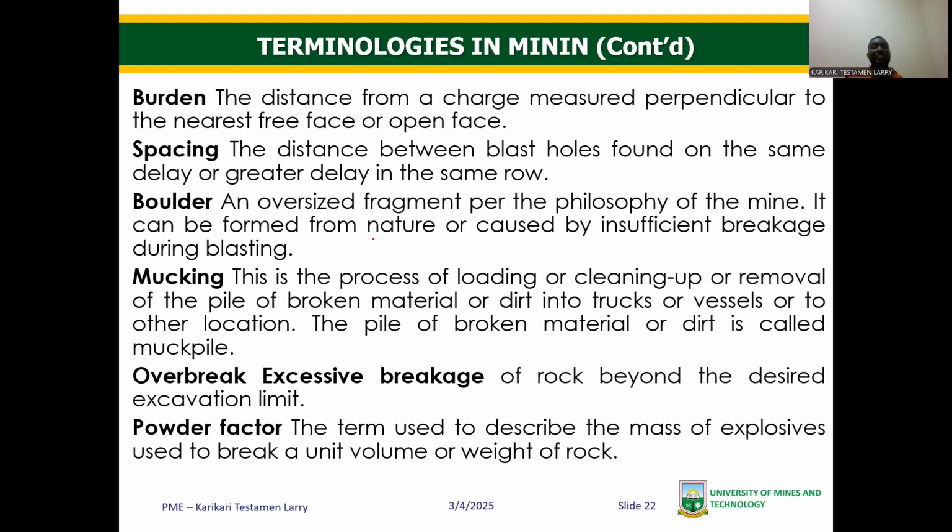Burden. This is normally under blasting. All these terminologies, the first two are under blasting. Let's tackle burden. We are drilling, and let's say this is our drill pattern. The distance from a charge measured perpendicular to the nearest free face or open face, that is burden.